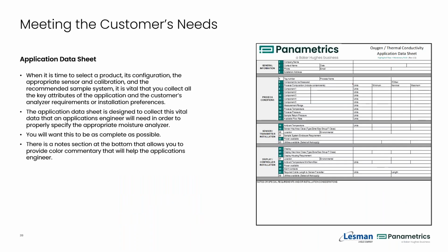So how do we know that the XMTCpro or any binary gas analyzer would work well? That's because we have to understand your application first. And what we ask for is that you fill in an application data sheet, which gives us all the parameters. Is this an explosion-proof area? What are the gases that you're looking to measure, one and the other? Can it be done using a binary gas analyzer? What is your zero gas going to look like?